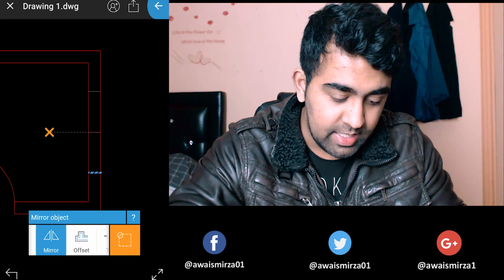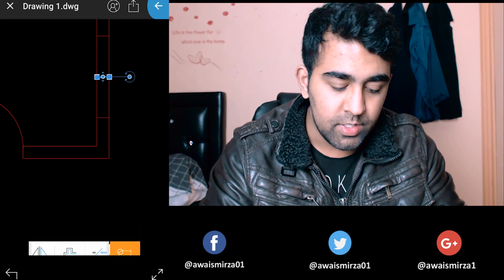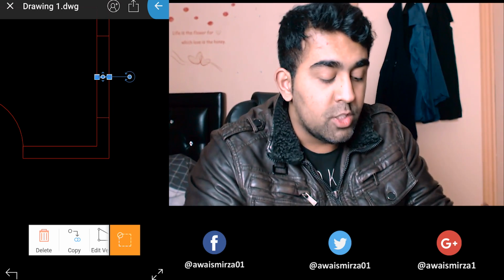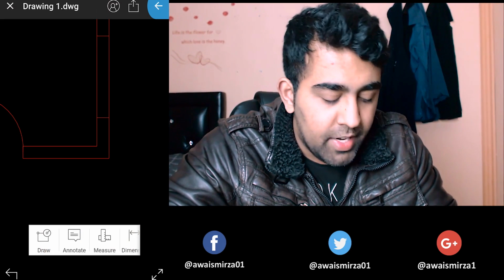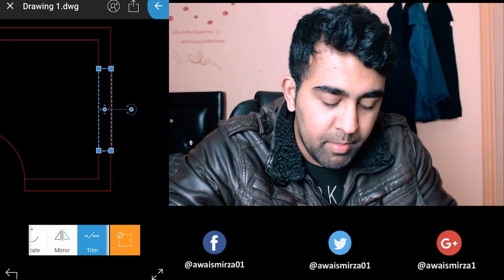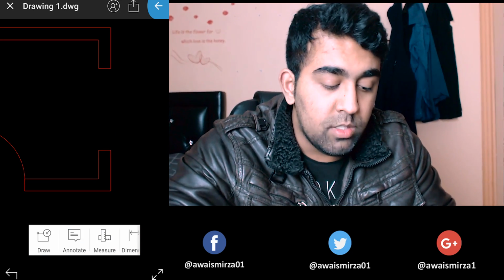Okay, so let's deselect everything by pressing on this yellow button, and then I'm going to get rid of this middle line. So select that, go to your modify panel. It automatically takes you to the modify panel here. So let's delete that line now, and now we're gonna use the trim command. Okay, so let me select this line and this line, okay, and then go and select that trim command, then get rid of this, right? Okay, well, you could make those line in the middle.